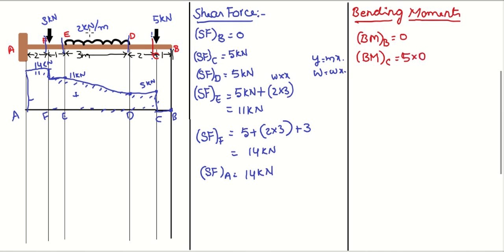And all the moments for a cantilever will be hogging, negative bending moments. So all the loads are causing the beam to bend like this. So that is called hogging. If you look like this, it is like a crying smiley, right? So it is a trick to remember again. Hogging, a negative bending moment, is a down curve, which is considered to be a crying curve. That is a negative thinker, always cries. So the bending moment is negative over here. It is just a trick to remember, but you remember hogging and sagging. Hogging is negative bending moment, sagging is positive bending moment.